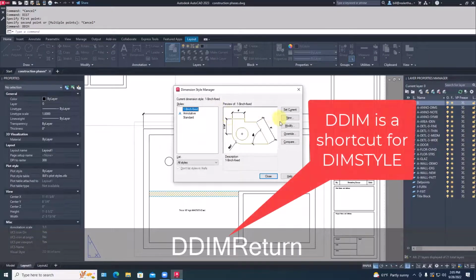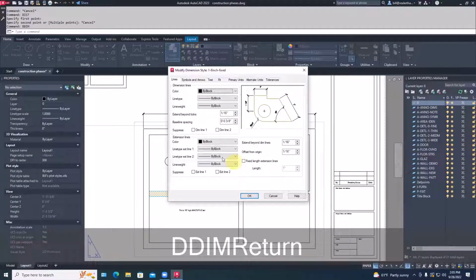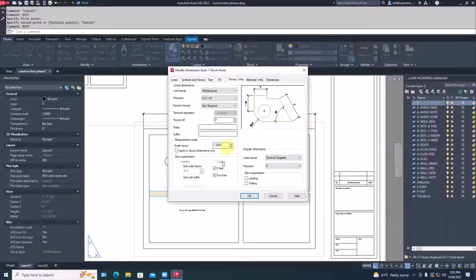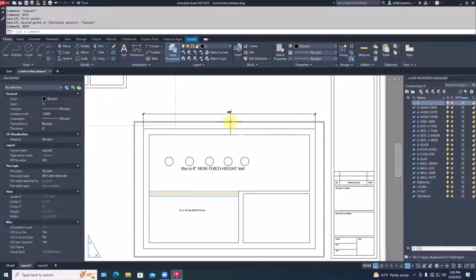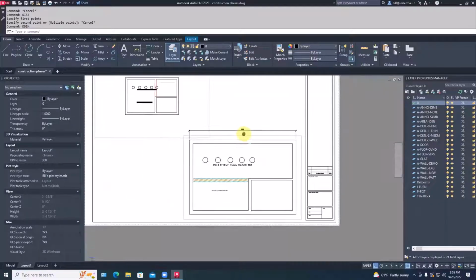So dimedit, modify units. It's set to save space if there's no inches on there, not to show the inches. I usually say, always show me the inches. If there's no feet, you can get rid of the feet. I don't need to see 0 feet, 9 inches. I just want to see the 9 inches. So, okay, close. So that goes back to 30 feet, 0.